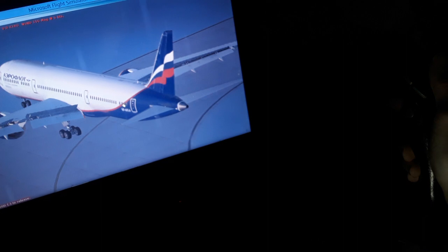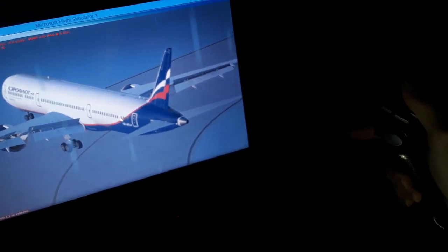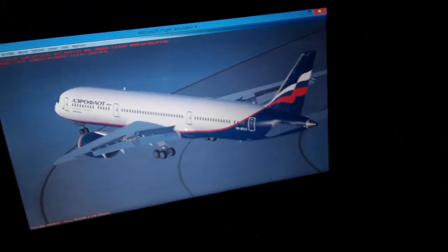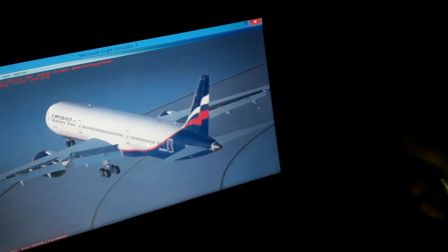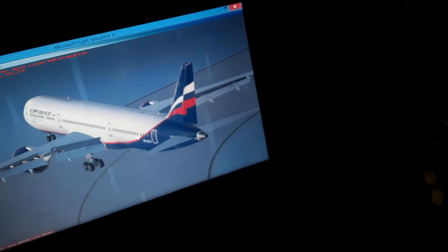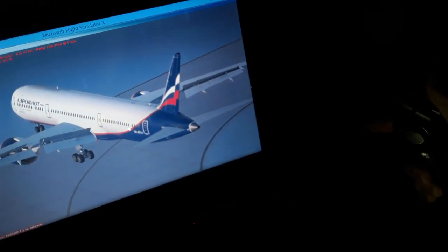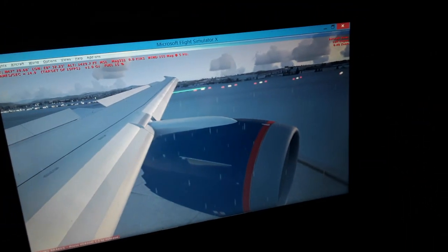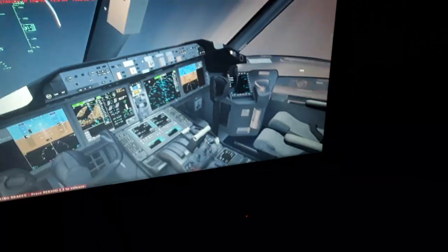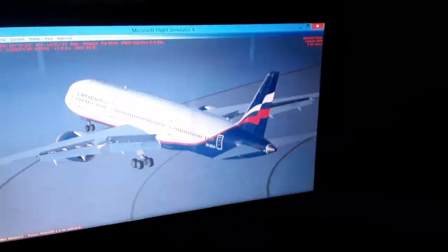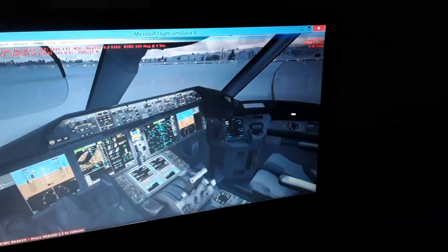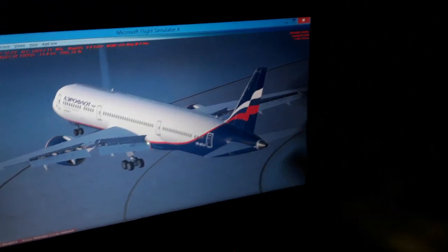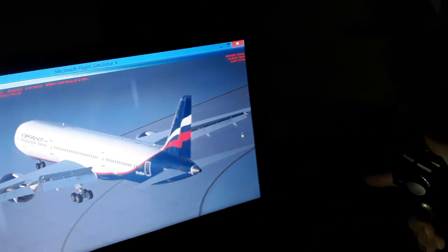In takeoff or in landing, the inverse is happening. As we decrease the airspeed, we have the forward nose wheel activated. So we have the rudder to control the aircraft above 80 knots or 144 kilometers an hour.